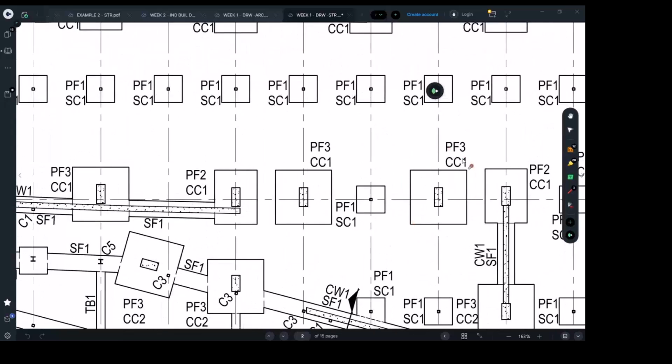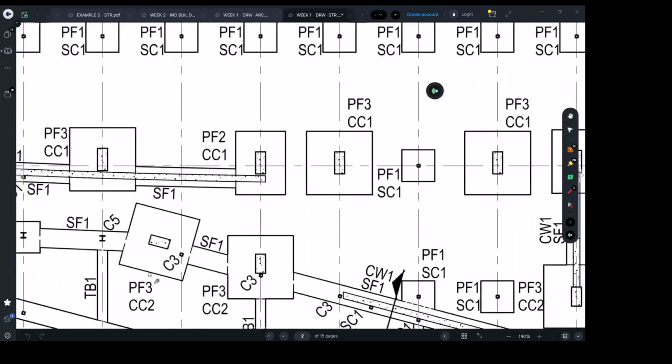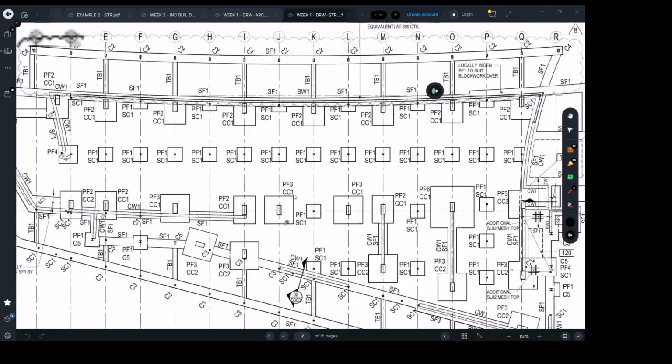Okay, so yeah, after the banded slab system, which gonna carry its own weight, the concrete slabs are supported on the band beams, and these two elements, they're gonna carry the above roof. They're gonna take the load through the columns. From the columns, they're gonna go to the main pad footings like pad footing 3, pad footing 2, and so on. And that's really the story. Same thing on this side.